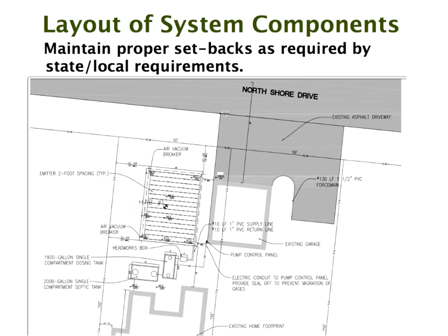dispersal. We do have one very large commercial system up in Emmett County that serves a restaurant, a very large restaurant that sees a lot of use during the summer, and that one is included with an advanced treatment system. They have some aeration units in series that flow down into a pump chamber that pumps into drip dispersal, and it's a huge field, and sandy soils. It's in a sensitive environment.